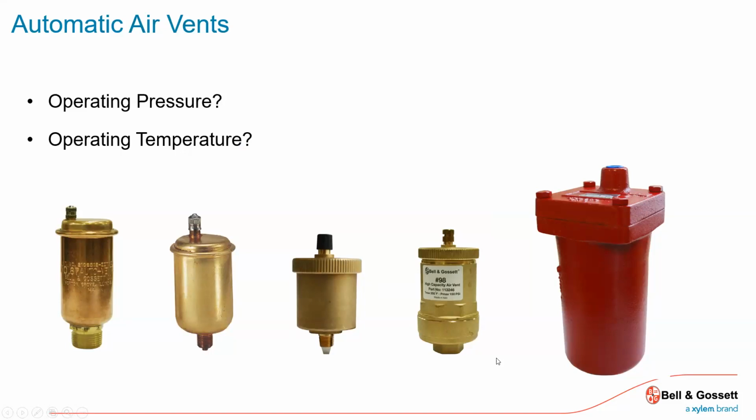And as that float inside there gets, I apologize, I'm showing the people in the room here, and I know you guys online can't see, but there's a float inside here. If the water around it gets displaced with enough air, then the weight of that float starts to drop down. As it does, it pulls on that lever, which opens up the port on any one of these devices. Now I've got system pressure behind, which pushes the air bubbles out. The pressure displaces the air, the float rises back up, the port closes.